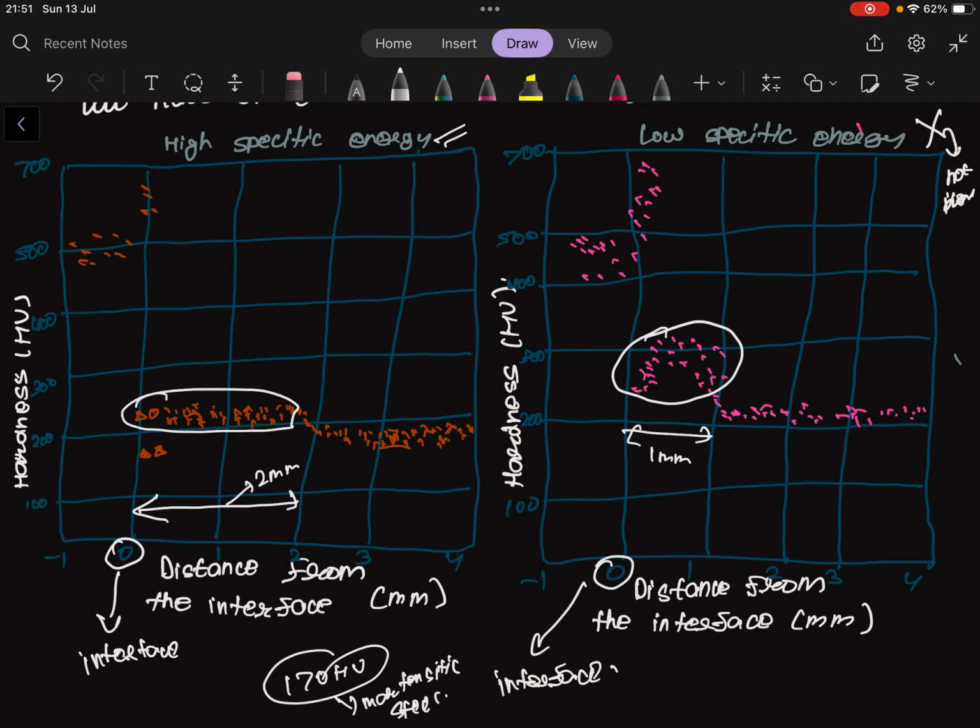If one wants to apply the component, we have a heat affected zone of only 1 millimeter here, but this one results in a higher one, like 2 millimeter. So we can think of applying a successive heat treatment like annealing to stabilize the hardness values inside our component.